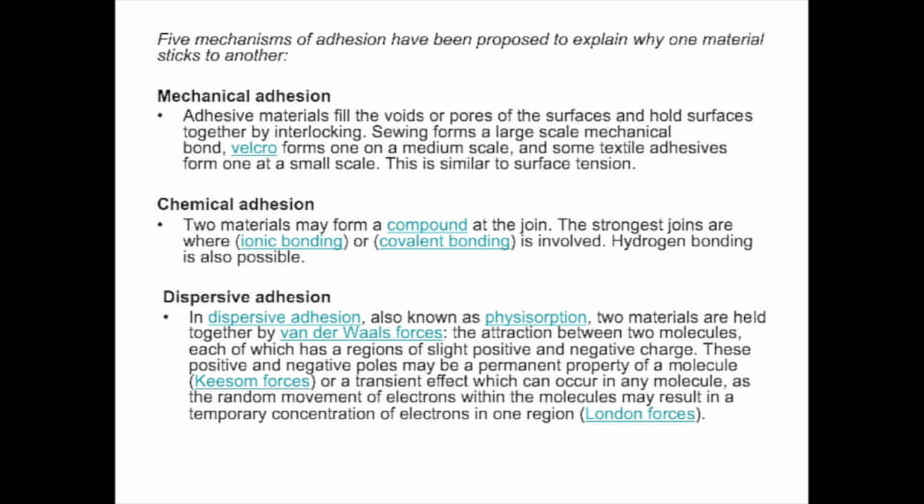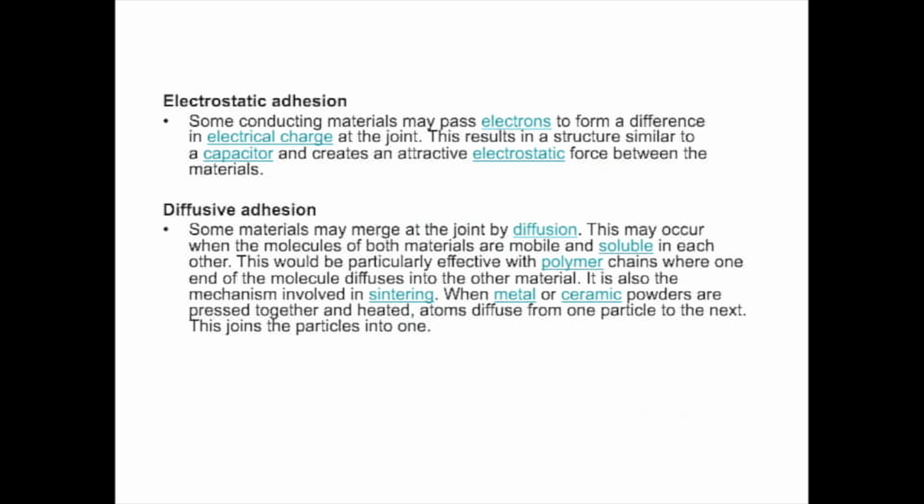Chemical adhesion means that you have non-covalent forces or the formation of covalent bonds that result in very strong binding or adsorption. Dispersive adhesion could be weaker forces or dispersion forces that promote adhesion. Electrostatic adhesion can be based on charge attraction versus charge repulsion. And then diffusion behavior could mean that a material, simply because it flows between two planes, means that you have a continuous attraction between those planes as long as the diffusive behavior of that adhesive material goes into place.